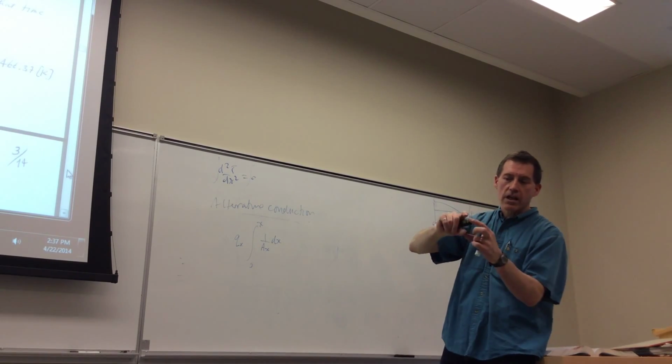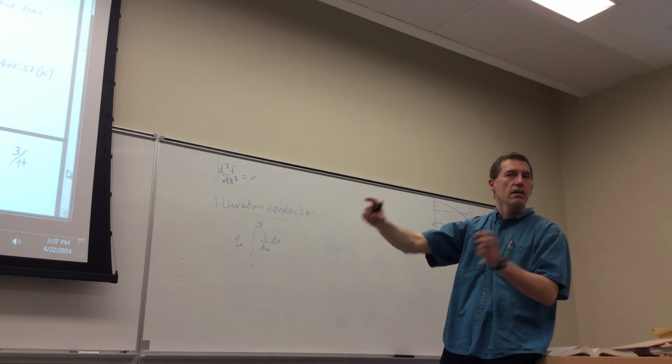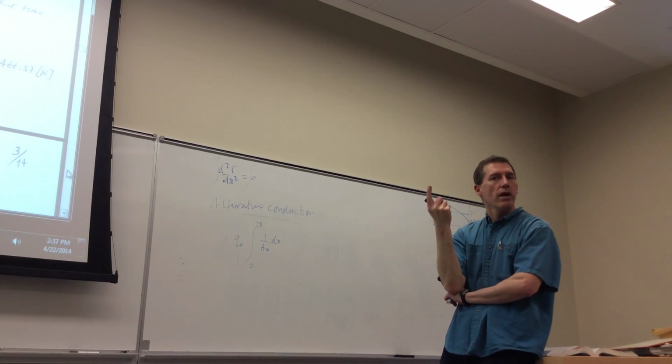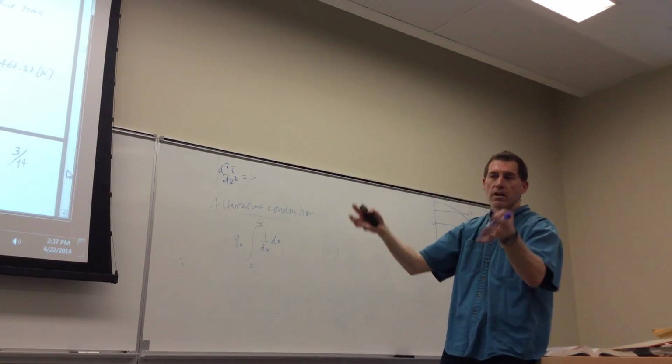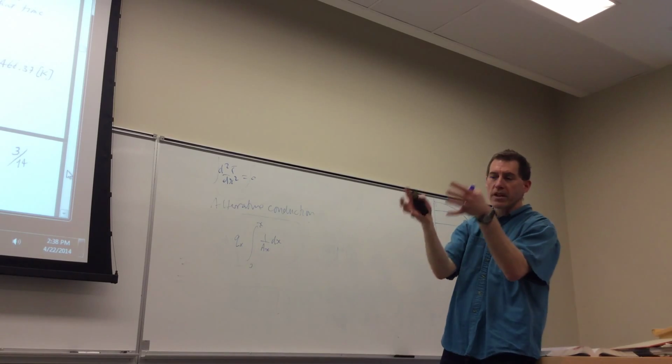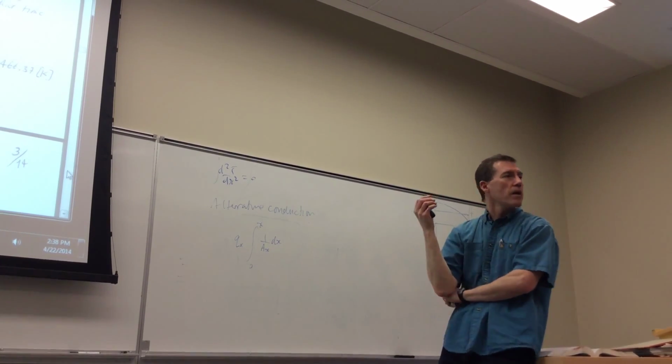And the interior calculation that you do for, say, the h on the inside, that's based on the mass flow in one tube, right? It's not the total mass flow for all tubes. I've had some people do that. They say the mass flow for the tube side is whatever kilograms per second, put that all in one tube, and get a giant, massive Reynolds number and way overestimate the h.